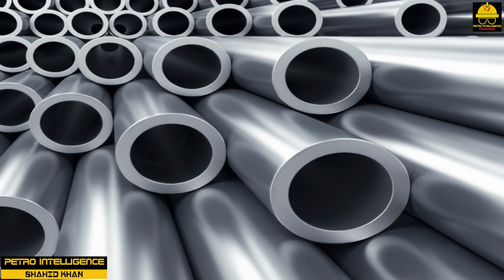The strength and resistance to oxidation, rusting, required for these conditions are secured by adding small amounts of alloying elements. Molybdenum in quantities as small as 0.5% greatly increases the strength above 900 degrees Fahrenheit or 482.22 degrees Celsius. Chromium is added in amounts up to 9% to combat the tendency to oxidize at high temperatures and to resist corrosion from materials that contain sulfur.